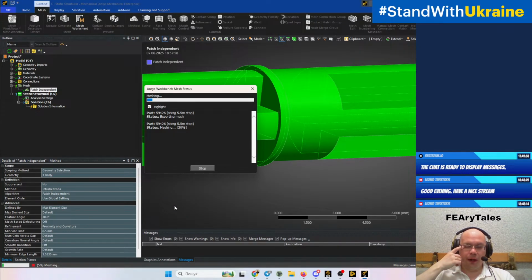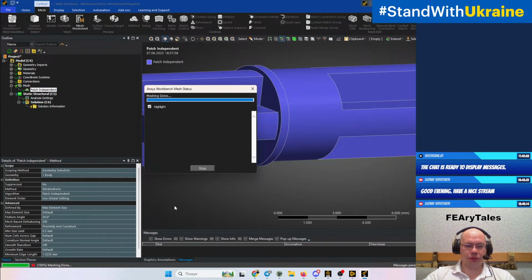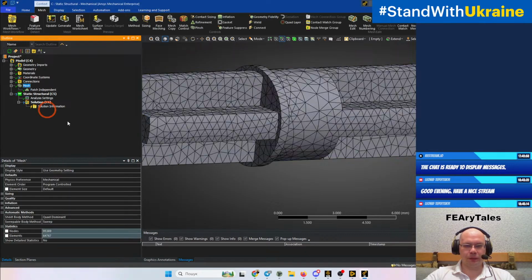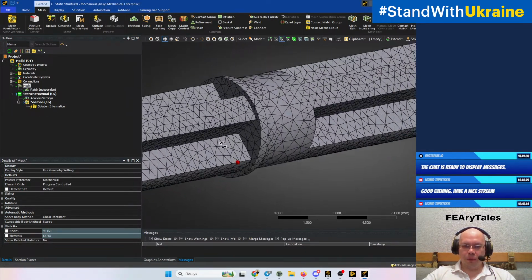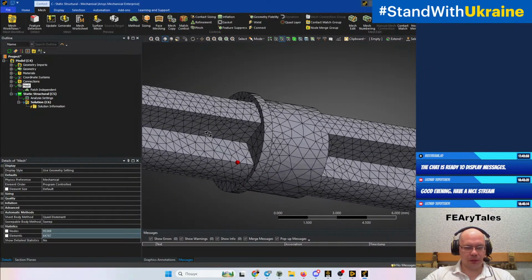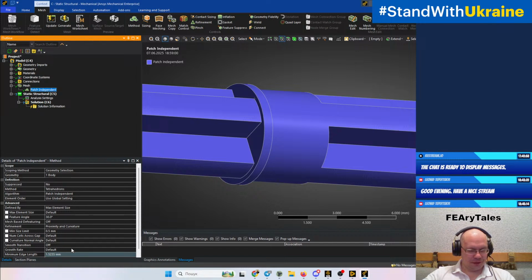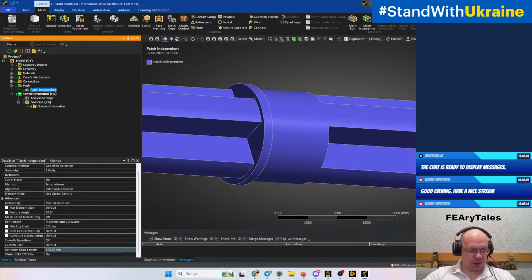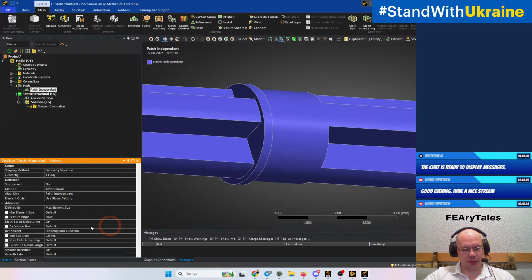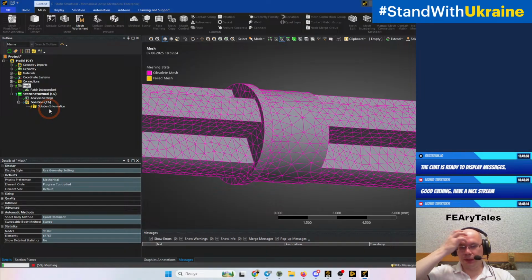This type of mesh creating takes longer than the patch conforming method. And nope, it does not create any type of simplification. Okay, let's add some addition where it's defeaturing. Mesh defeaturing is off. Let's turn it on. So defeaturing size 0.5, the same, and let's generate.